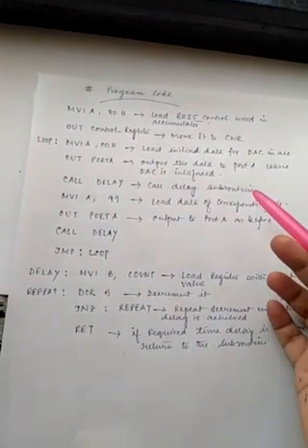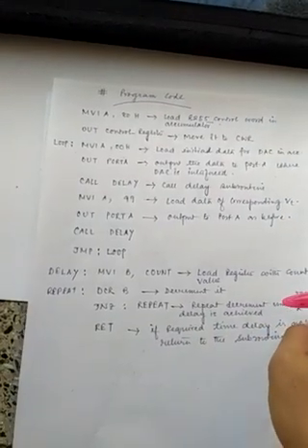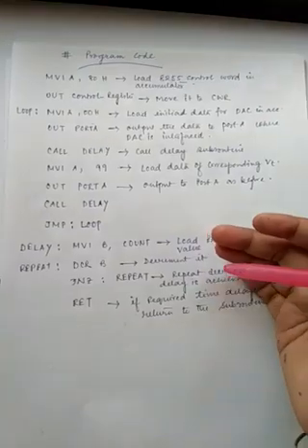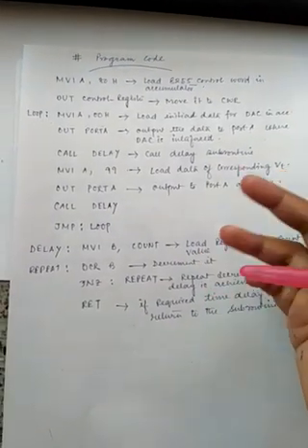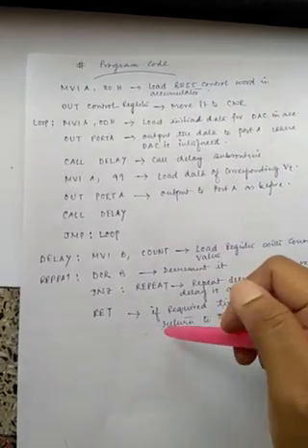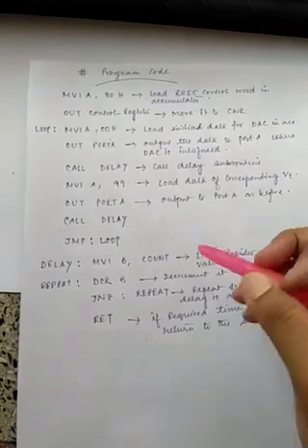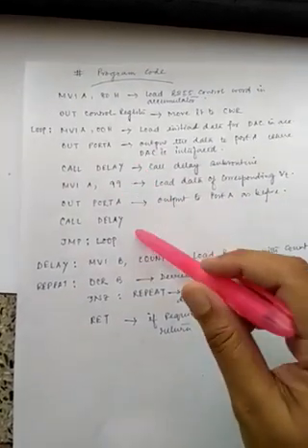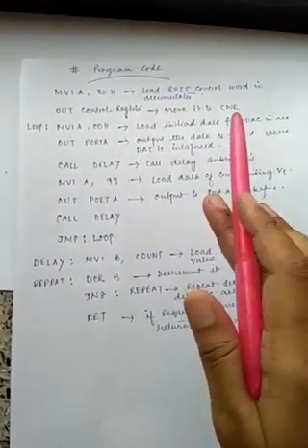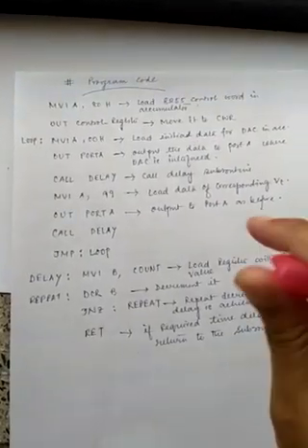In the 8255 part, I have already shown what the programming code is and how to take the value in the control register, and how to send the value to the control register and to some ports. What is the instruction? Because there is a sending instruction, a transferring instruction, and a taking instruction, and transferring instructions to the input port or output port. So the instruction will be OUT or IN, but that portion I have already shown to you in your class, and that will be implemented in our subroutine programming also.